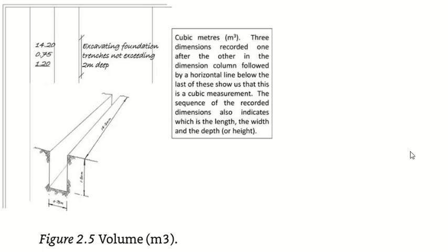It is written because of the standard method of measurement. If you go to excavation of foundation trench, you will see in the description that if you are doing a foundation trench, then you have to mention in the description that this foundation trench is less than 2 meters.